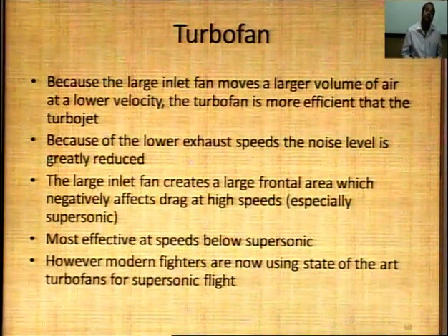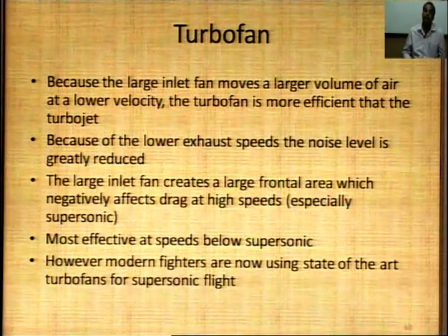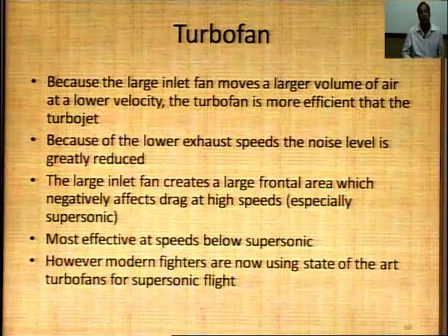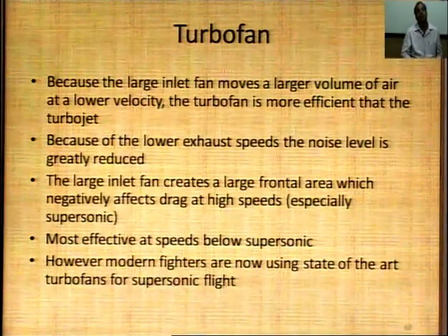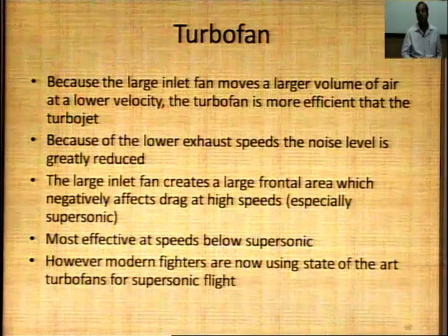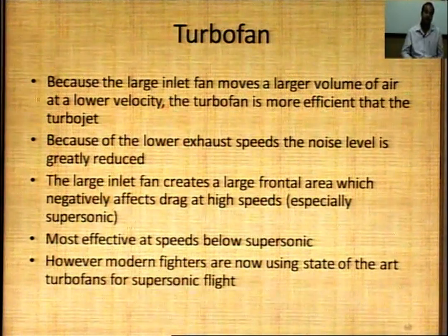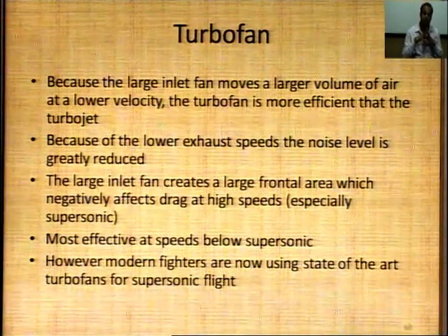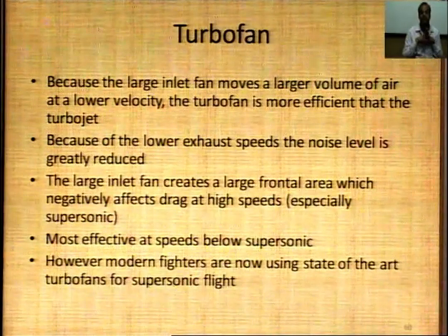Turbofan. As compared to the turbojet engine, the turbofan is somewhat more efficient. First, let me discuss the point. Because the large inlet fan moves a larger volume of air at lower velocity, the turbofan is more efficient than the turbojet engine.